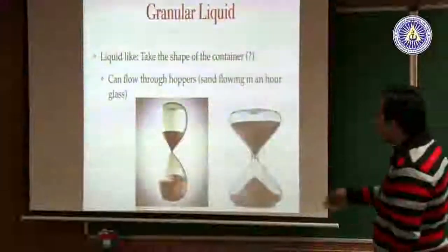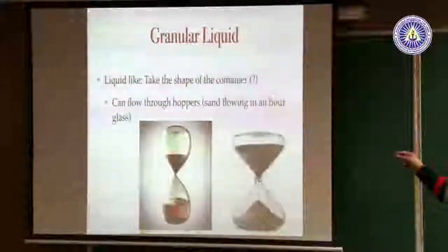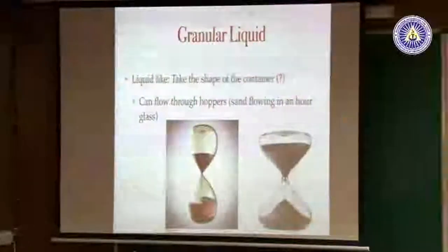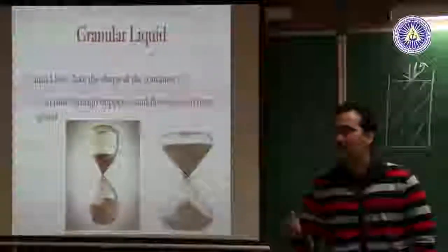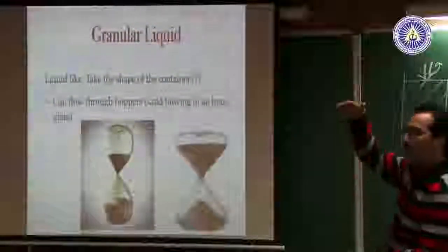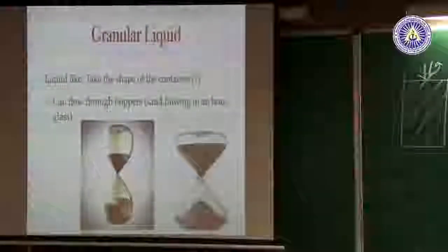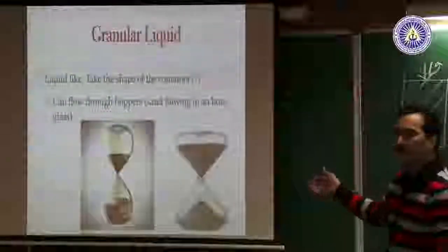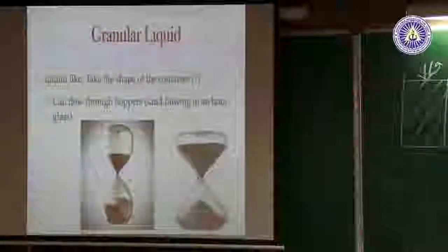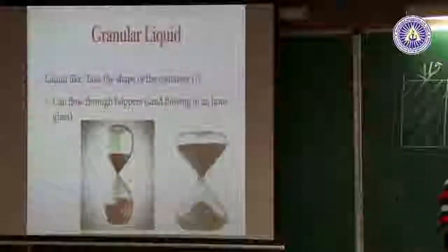Not just that, they can also flow through an orifice. We did this demo yesterday, and they'll keep flowing in an hourglass. In fact, the flow rate seems to be independent of height, which means if you're measuring time, the time is independent of the head. Your flow rate is independent of head, and so this is a linear time measurement device if you want to build one. If you had a fluid, then whatever you are collecting depends on your pressure head, and that's why a fluid hourglass is not that popular.